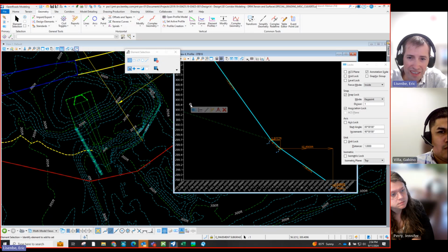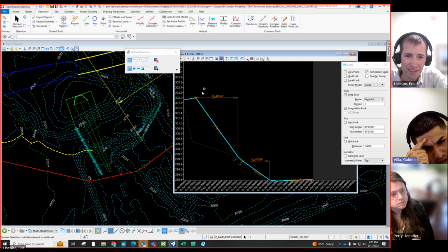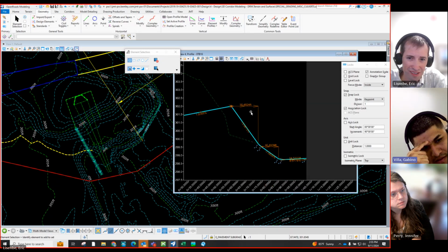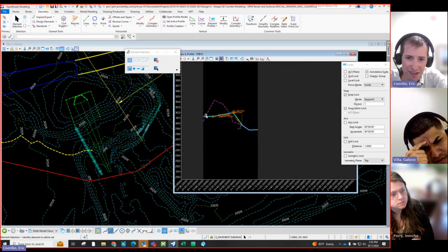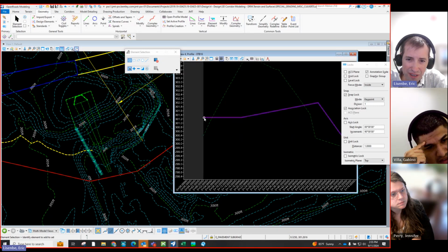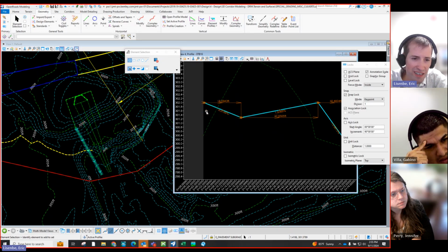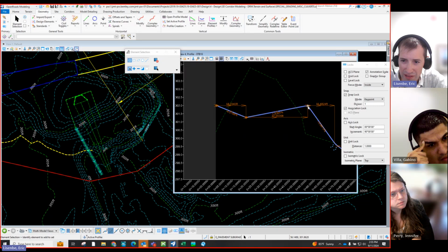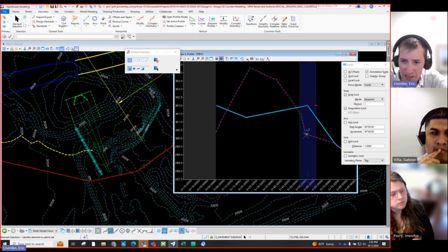Give it an elevation. There we go. 302. So is that 302? Are we just kind of estimating something higher than the flow line? I want this one to be 302, because that last line I drew here, I had 302. I had it in there because we were coming off the slope. And then this one, I actually did want that one snapped to existing ground.